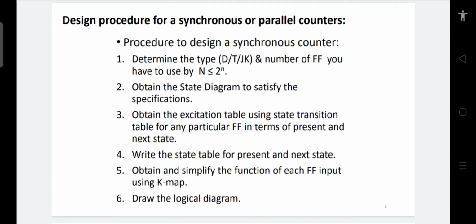So that is an easy thing, but in this type of counter we have to design the circuit, because we do not connect the output of the first flip-flop to the clock input of the second flip-flop, as we did in the asynchronous counter. Rather than connecting the output of the first flip-flop directly to the input of the second flip-flop, sometimes we have to connect some combinational circuit in between to get the proper function. So that is why this type of synchronous counter is a little complex to design. Whereas, as all the flip-flops of the counter get the clock pulse simultaneously, these counters are fast.